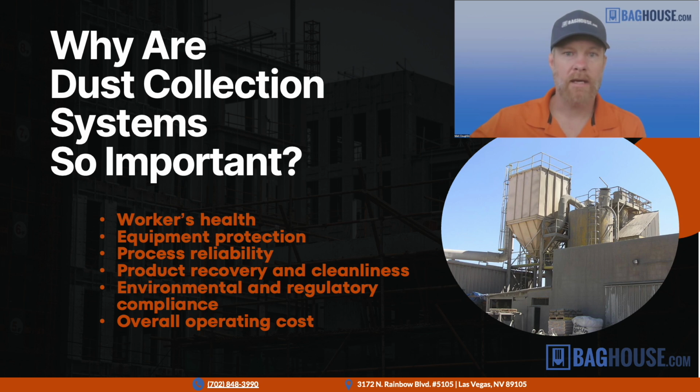And then next slide here. So, why are the dust collection systems so important? And what does it matter if it's dusty? It's a dusty process, right? Well, there's a number of things. First off, workers' health, right? You have employees out there that are potentially subject to exposure to respirable silica and respirable fine dust. It's terrible for your lungs. You don't want your people to be subject to that, right? So adequate dust collection will mitigate that.